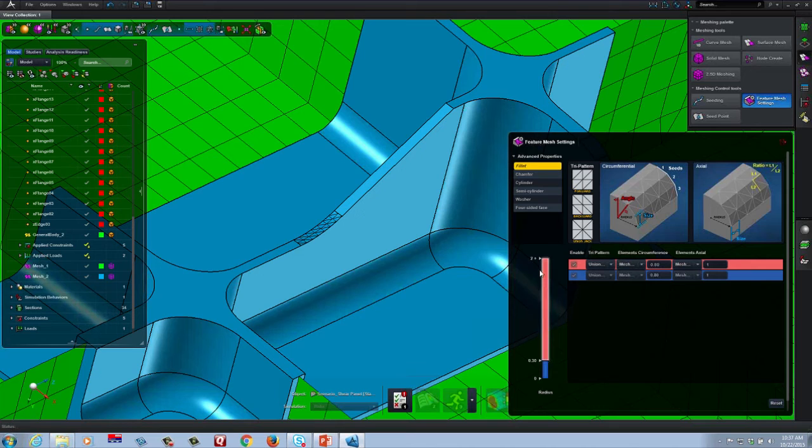I remember I had, we'll make this a 1. I remember I had about 1/8 of an inch. We'll do something in there. I had 1/8 of an inch, we'll do something in that area. And I had basically 1/4, so we'll do something in that area. For this one, I want, let's say, 5 elements or maybe 6 elements around the face. And in this one, perhaps I just want 3 for the smaller one, so we'll do 3 there. All right, we'll turn that off.